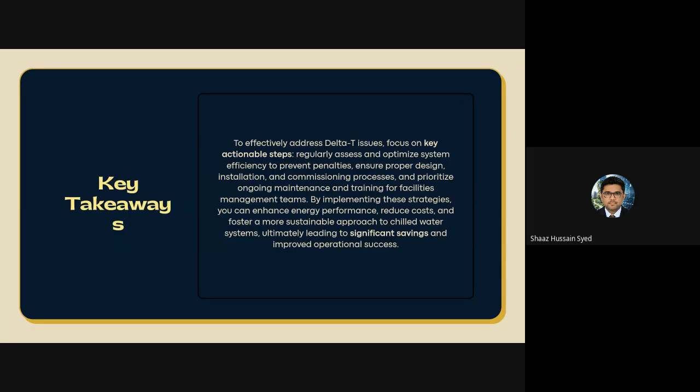They see that the pumps have to run faster, they see that the temperature is not efficiently utilized, and they bill you accordingly. The causes of the delta T problems that we see every now and then are dirty filters, wrong valves, improper sizing of coils, and bad sensor placements.